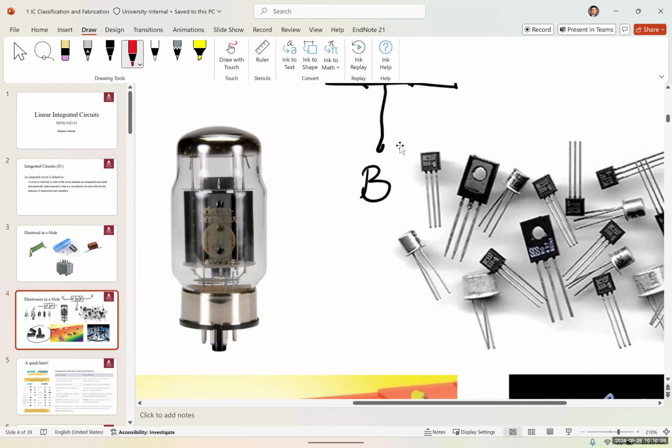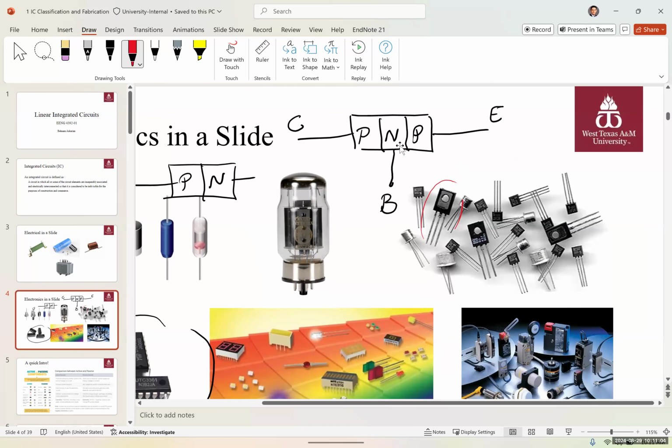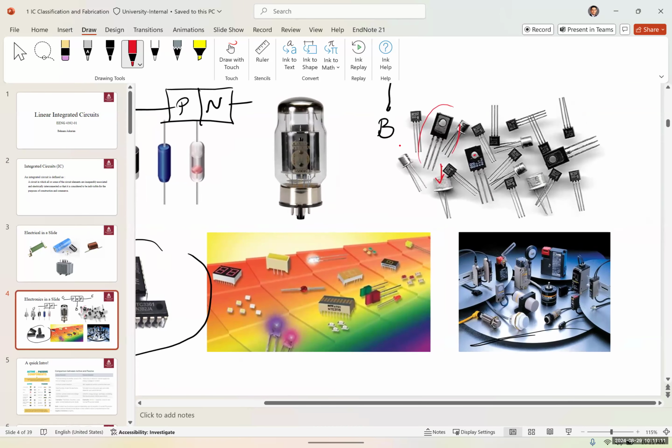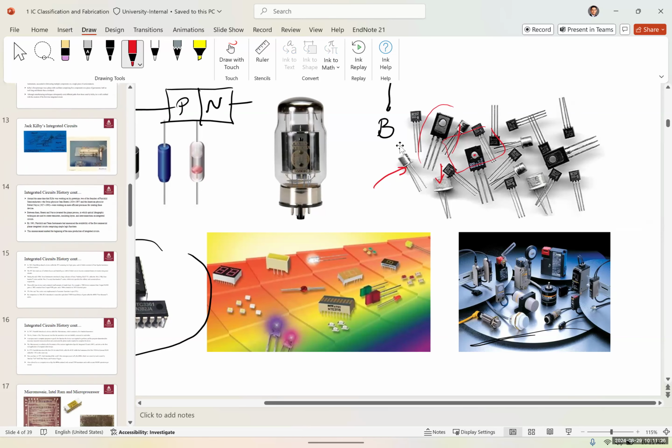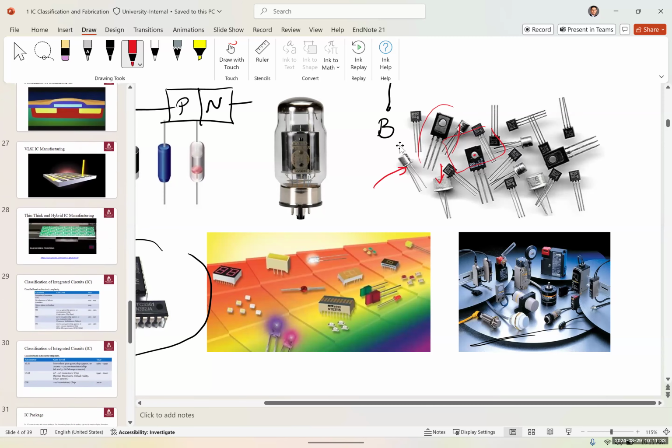Do you know why we use a metal on one side, why we use a metal casing? Yes, perfect. These are spots where you can connect a heat sink to it and screw it to them. Usually for power regulators, we need to connect a heat sink. And some of these casings, like these transistors, are made out of metal because metal is better at heat dissipation. So we use a metal casing to be able to cool them down.